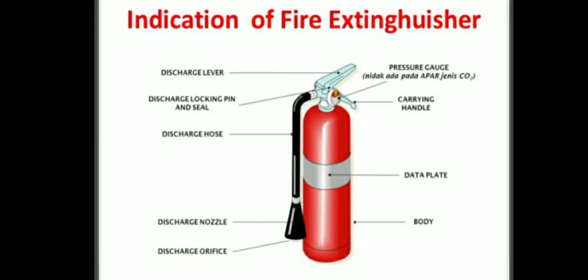So it should not happen that by small lifting up, the CO2 cartridge inside bursts and the water or whatever aqueous foam comes out. Generally the pin is there, we have to remove this pin, then only we have to press the puncture, press and puncture it.